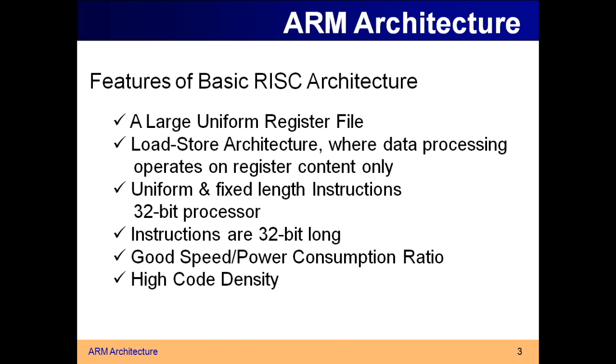Then similarly you will be loading the second number from memory to a register, that is known as load operation, right? From memory you are loading to the register. Then you will be performing the operation in the ALU. Finally the result will be stored back to the memory, that is known as store operation, right? So like that the load and store operation will be done. So it is known as load store architecture.